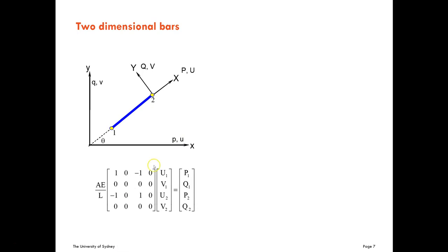So this is the element matrix equations of this structure. Notice that I just add zeros behind the degree of freedom corresponding to the displacement in the perpendicular directions of the bar. So if you multiply this by this equal to this, and this by this equal to this, you recover the equations of the one-dimensional bar.